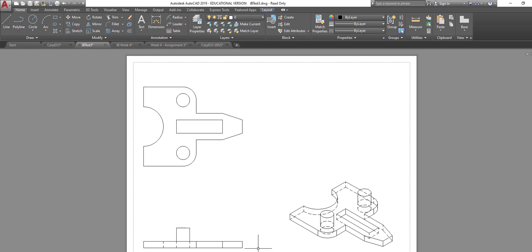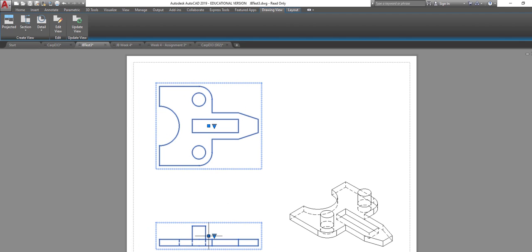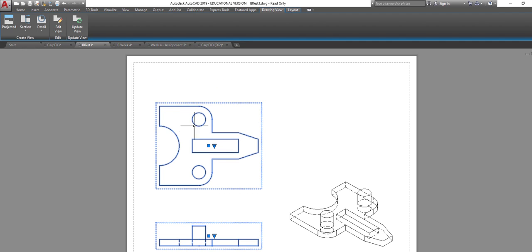Now we go into the 2D wireframe. And in this case, it's showing us hidden lines. And here we can see that these dowels weren't done all the way to the bottom, where they should have been, and it would show one solid piece. Anyway, from there, if we need to, we can adjust and move this over slightly. Okay. Since this is not the base point, we're going to set this here. Let's do this one. This is the base one, which will bring everything over. Okay, and then let me bring this one down just a smidgen, and we'll pull all of our dimensions up here, back here, and out here. Okay, so we're at enter.